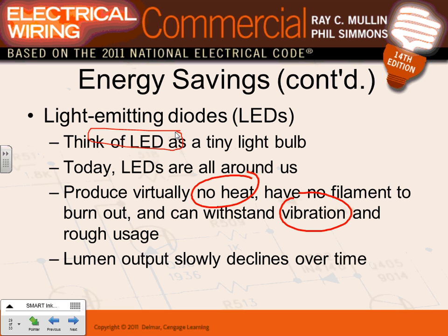There's a drawback. The lumens, like everything else, guys, slowly decline as you age. As a fixture ages, the lumens go down. The challenge is how fast it goes down. For example, Aaron, your energy is going to go down. Are you going to lose most of your energy at age 50 or at age 65? That's really what makes a fixture a good fixture or a bad fixture: how long that fixture can hold most of its lumens.